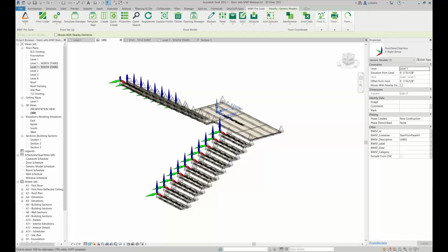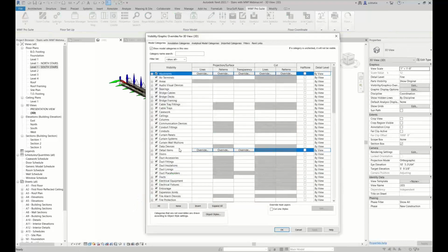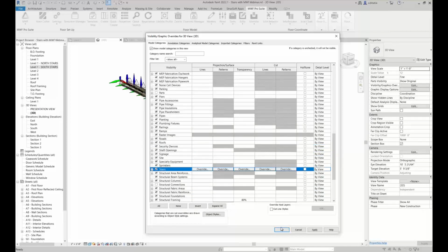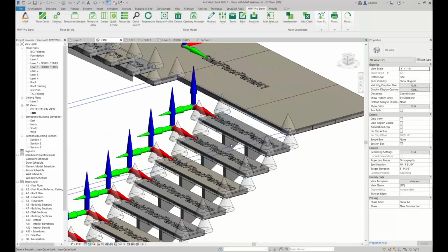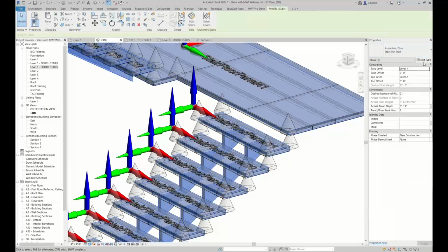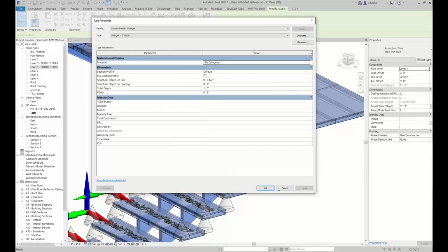Hi. So basically, you were asking if there's any advice for framing a support stringer. Well, if you use the stairs reference, so let's go ahead and show our stairs back. If you use your stairs, like these ones, the ones we used as the reference, if I click on my stairs, instead of actually drawing it with a carriage, how I just currently did, I can actually use a support stringer over here, and I can choose the size and shape of my stringer here.